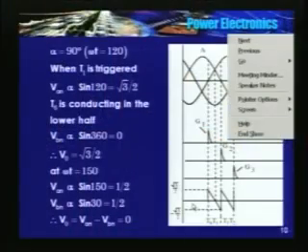So in this waveform, this is positive L di by dt and this is negative L di by dt. Current starts from 0, reaches a peak here, because at this instant L di by dt is 0, so current has to be peak, and again comes down and becomes 0. It's just at the boundary between continuous and discontinuous.